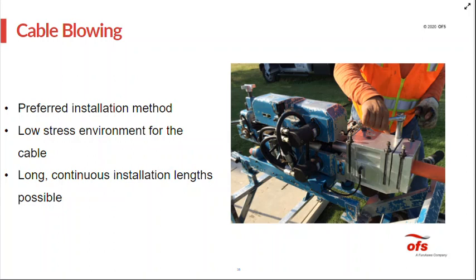Okay, I'm going to move on to blowing. Blowing is actually the preferred installation method. A blown installation, in contrast to a pulling installation, uses distributed installation forces. So you can avoid the high concentrated force that's applied to the cable when you're pulling the cable. So it results in a low stress environment for the cable. And also it allows for long continuous installation lengths compared to pulling the cable.